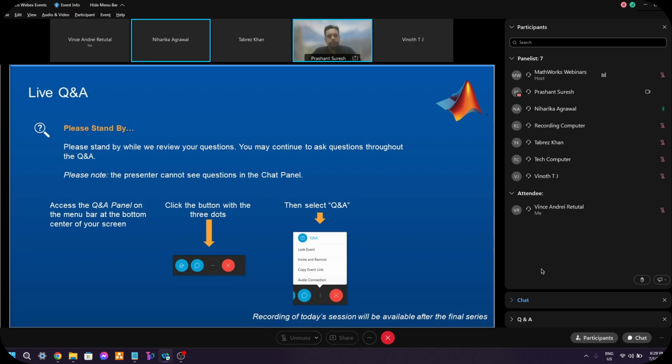The first question we most commonly get is: do we support Xilinx Vivado for co-simulation as well? Currently, we support a complete automated HDL co-simulation setup for Mentor Graphics ModelSim or QuestaSim, and Cadence. We currently do not support Vivado, but there is a continuous focus on this area at MathWorks, and you will be able to see soon that we will support Xilinx Vivado as well for co-simulation.